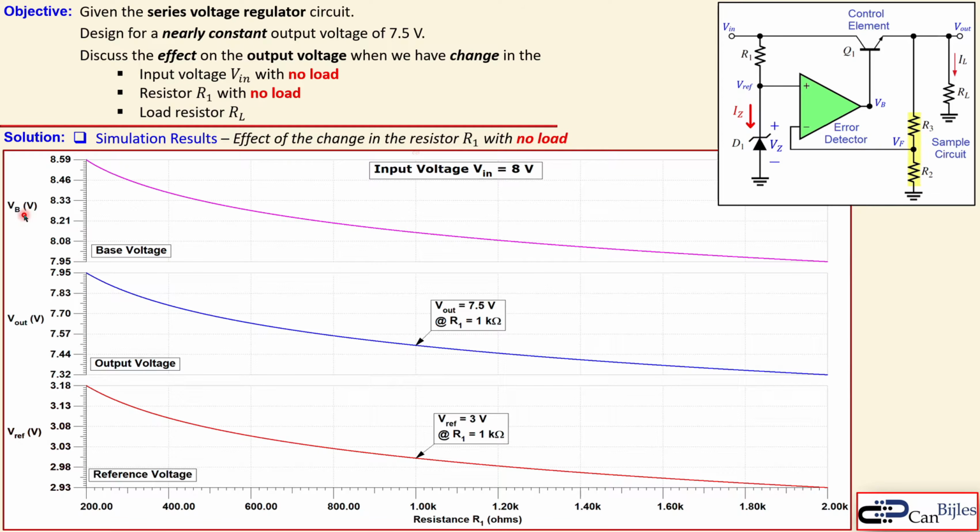Now we can also see what the base voltage is doing. Again, this base voltage is some voltage drop above this output voltage. So you can see here this voltage is the base emitter voltage drop plus the Vout here. So if this is, let's say, 0.7 in the standard form, then you will have this voltage plus 0.7 will be here.